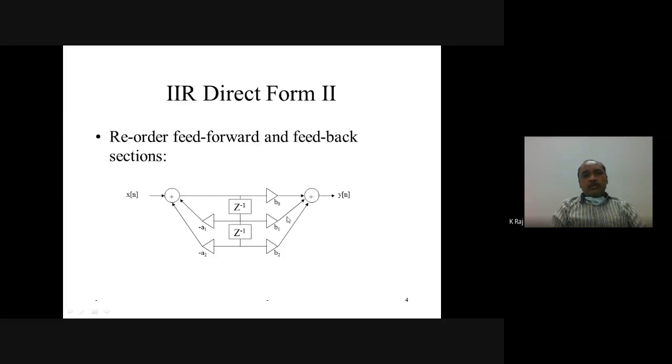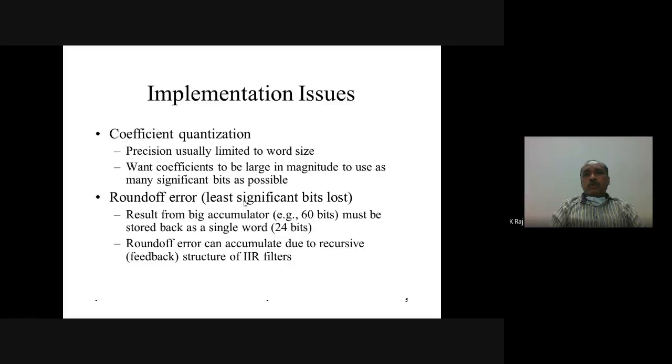What we have done in this one is we have reordered the feed forward and the feedback section, and now we are getting another architecture that is named the IIR direct form 2 architecture here.